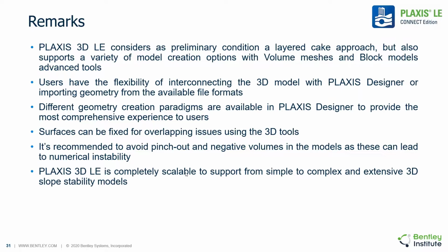Here are some remarks referring to our session. PLAXIS 3D LE considers a layer cake approach as the preliminary condition, but can support a variety of model creation options such as volume meshes, block models, bedding guides, and others. The users have the flexibility of interconnecting the 3D model with PLAXIS Designer. Different geometry creation paradigms are available in PLAXIS Designer to provide the most comprehensive experience to users. Surfaces can be fixed for overlapping issues using the 3D tools in the software, and it's recommended to avoid pinchouts and negative volumes in the model, as these can lead to numerical instability.